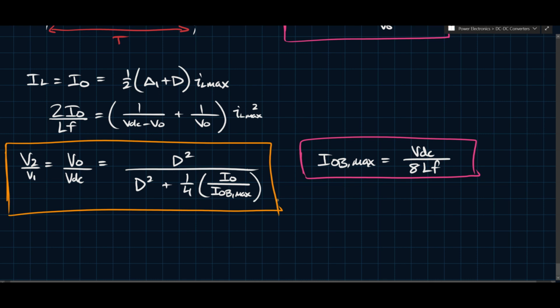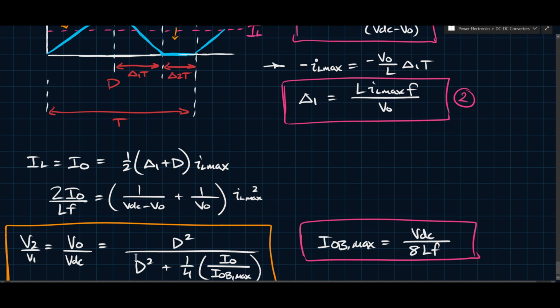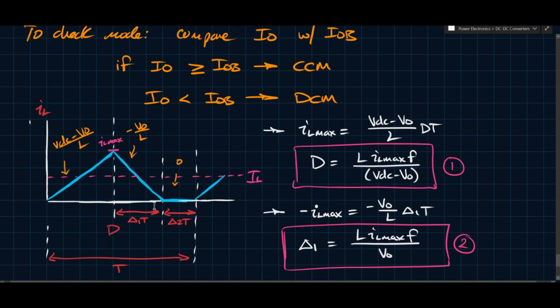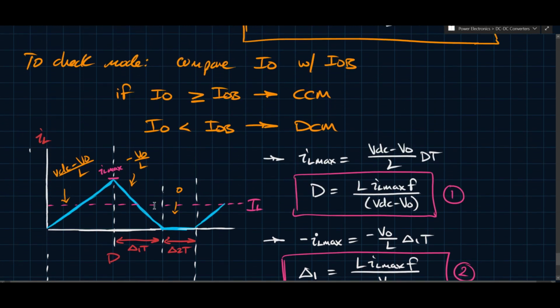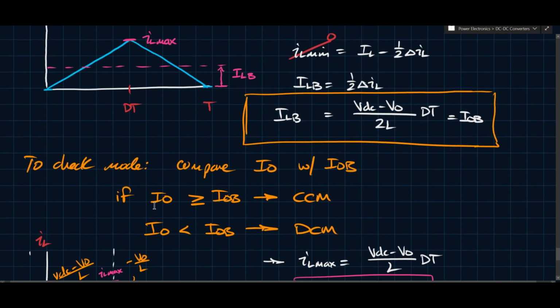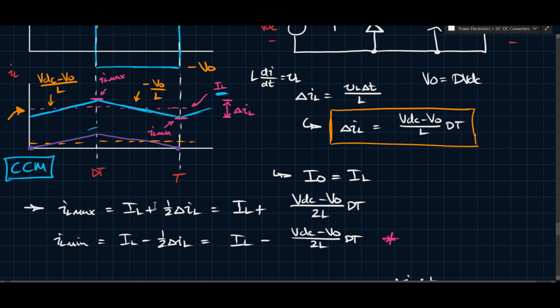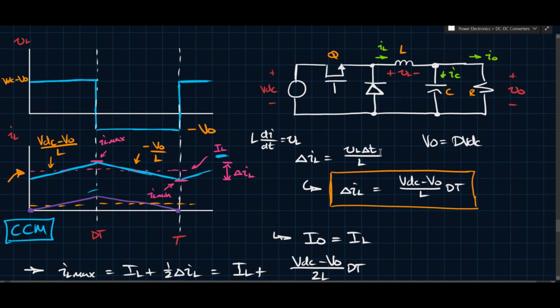So we have here this discontinuous conduction mode sort of operation of the buck converter. Here's what we've seen, right? So now we have this expression here. You can calculate that. You can plug it into there. You can determine what your conversion ratio is, if you're in DCM. We'll look at some examples of how to actually determine which mode you're operating in a practical setting. But for now, to just recap what we did, we've taken a practical buck converter and